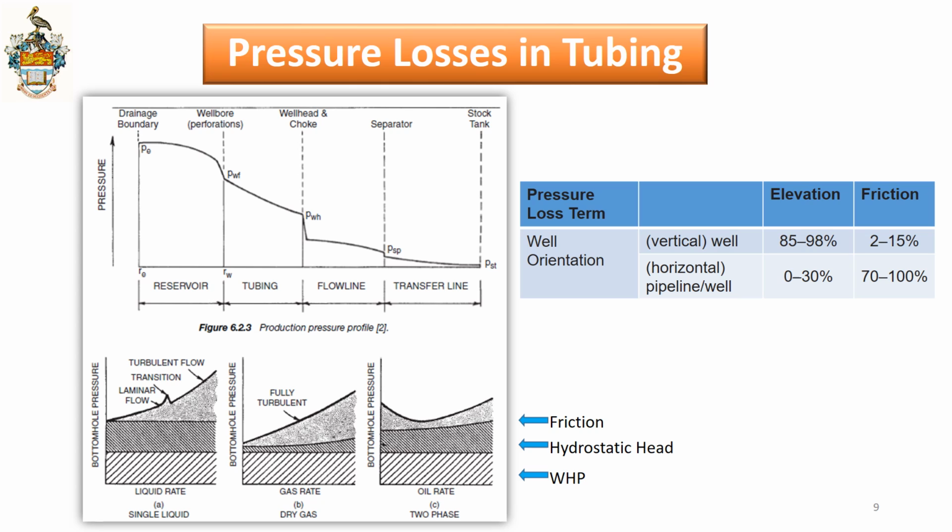And the other component that makes up the pressure loss would be due to friction. And as the liquid rate increases, you move from laminar flow to transition and ultimately to turbulent flow. And as you can see with turbulent flow, the change in the slope is increased, and that's because with turbulent flow you have more pressure loss attributed with that type of flow regime.